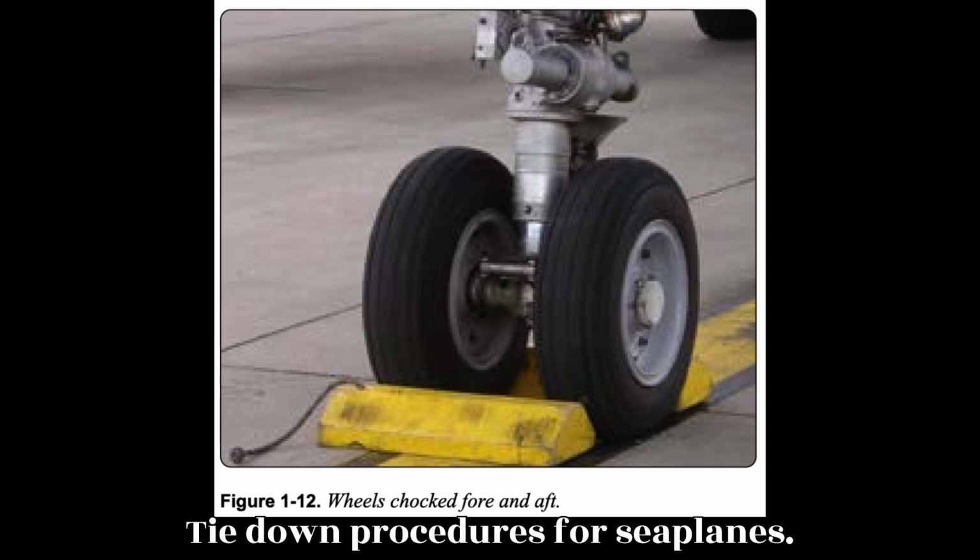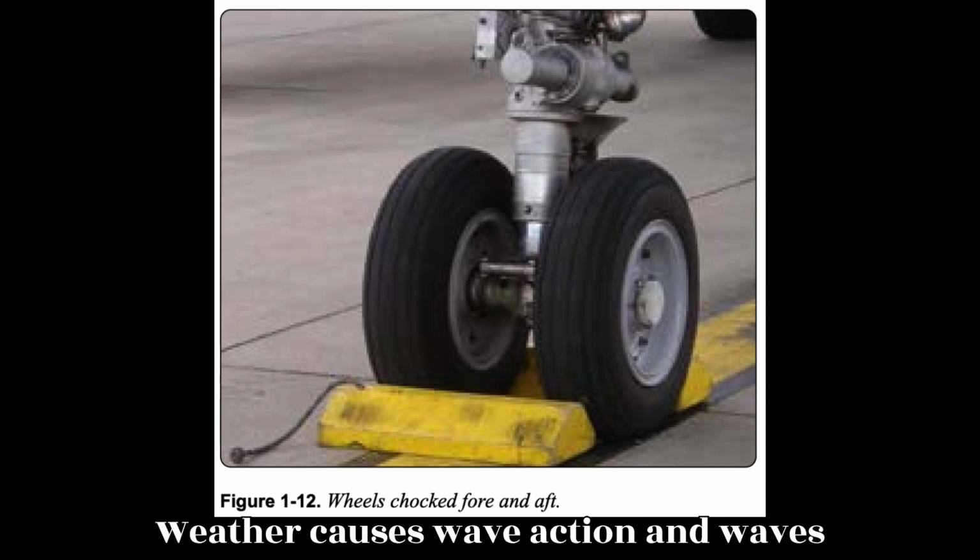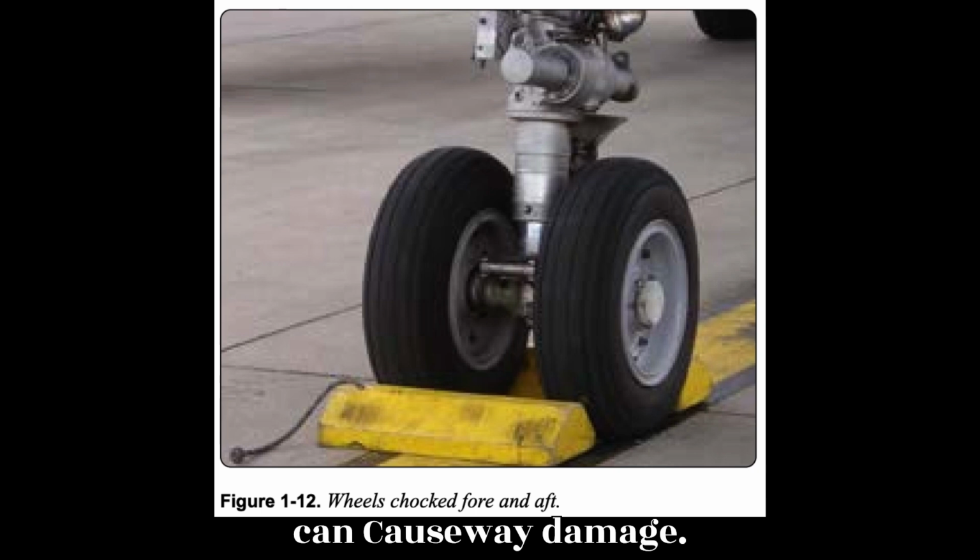Tie-down procedures for seaplanes. Seaplanes can be moored to a buoy, weather permitting, or tied to a dock. Weather causes wave action, and waves cause the seaplane to bob and roll. This bobbing and rolling while tied to a dock can cause damage.